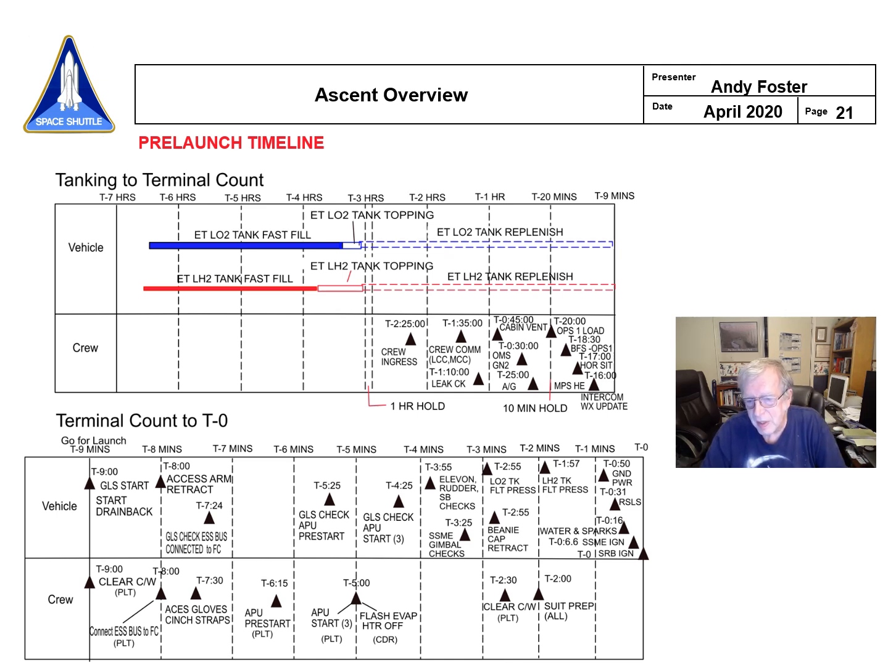At 16 seconds before liftoff, you see the water deluge to protect the pad from acoustics, and then the sparklers come on because essentially the hydrogen's been recirculating through the main engines to kind of keep them thermally conditioned. Some of that can gather right around the main engines, goes out through a little vent, if you will, in the nozzle, and the sparklers come on to burn it off, so you don't have so much out there that when you light off the main engines it goes boom.